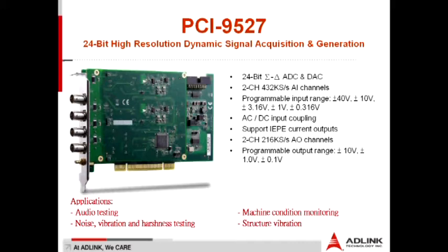Besides the analog input, it also has two analog output channels, allowing users to output self-defined waveforms, which means output of any kinds of waveforms, making it more convenient to use as an audio signal source and for full system integration testing. There's also an external digital trigger input-output connector, allowing analog input and analog output operations to be triggered and started with an external device.